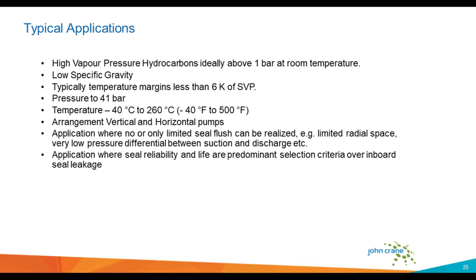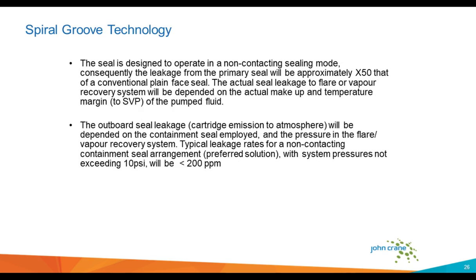Arrangement, vertical or horizontal pump. Application where no or only limited seal flush can be realized. Limited radial space, very low pressure differential between suction and discharge. Application, again, where seal reliability and life are predominantly selection criteria over inboard seal leakage.